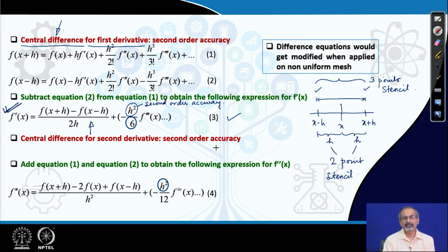Now, you may be wondering why we are not talking about higher derivatives. For example, the Navier-Stokes equation has second order derivatives in space. So, if we look at second order derivatives, can we have a way of discretizing them using the finite difference technique? Yes, we do, and we are going to show one such discretization where the accuracy is second order. So, the second order central differencing for the second order derivative looks like this.